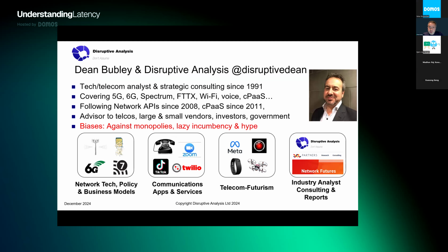And to give you a quick explanation, this is how long you have to wait after a busy channel use, how many slots of 9 microseconds. This is the minimum random number, the maximum random number you have to use to wait and to count back. And then this is the time that you're allowed to send. So this is the transmit opportunity. So you see the different numbers.